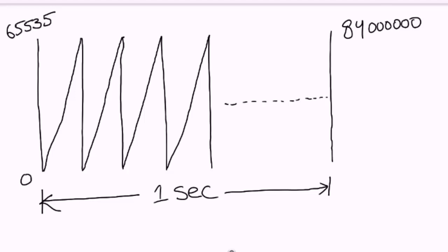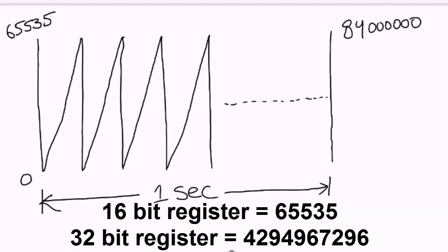It's because the register where this number is stored and incremented is a 16-bit register. So on 16 bits, the maximum number you can store is 65535. Now you must be wondering that this is a very hard limitation. It will stop us from doing many things. Well, in reality, it's not. We can still do any timing events with this. Now here we have chosen timer 3. But if we choose other timers, let's say timer 2 or timer 5, then it has a 32-bit register. Hence the maximum count it can do is 4294967296. Hence a very big number.